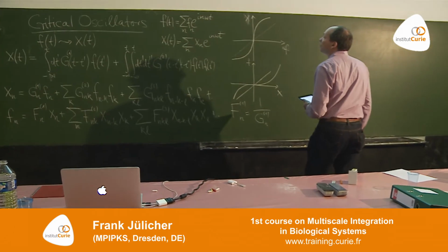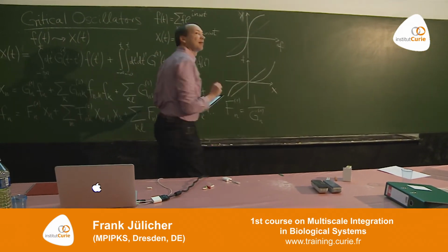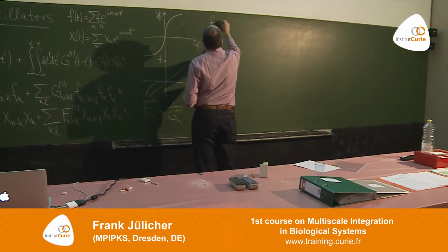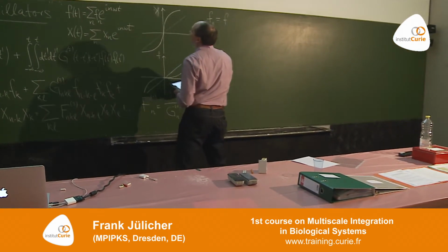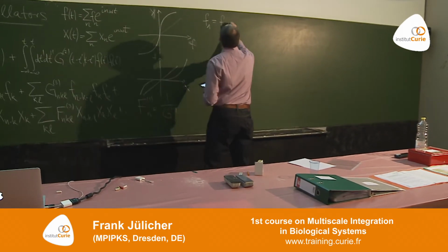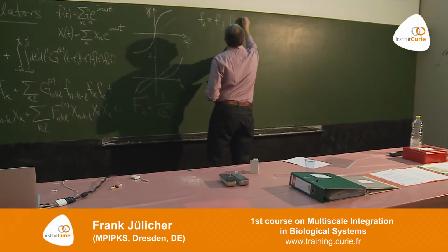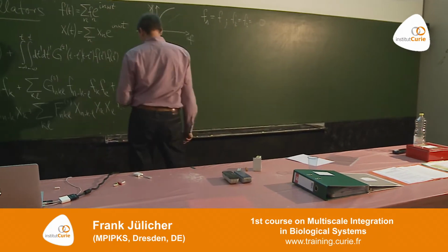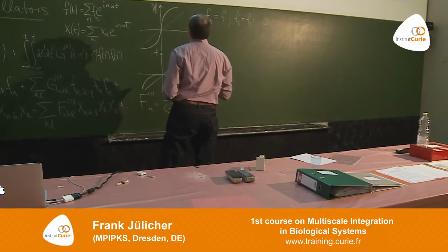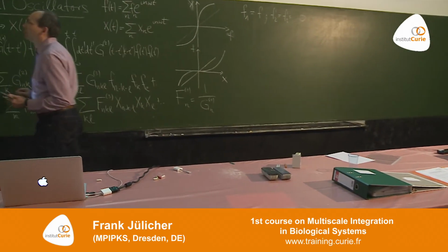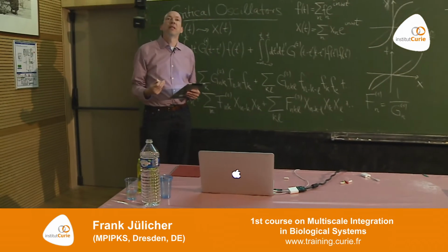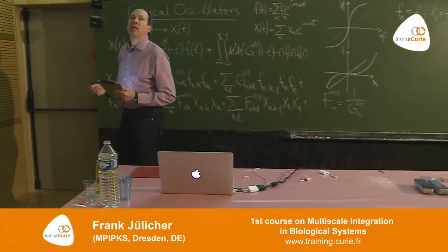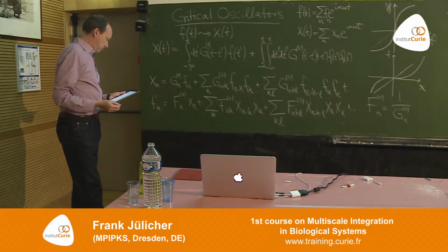So for simplicity now, I'm taking a sinusoidal stimulus. So F1 is my external force amplitude at frequency omega, and all the higher Fs I put to 0. Now, in general, the system will, because it's nonlinear, produce a response at the stimulus frequency omega, but also at all the higher harmonics. So I have, in general, xn.